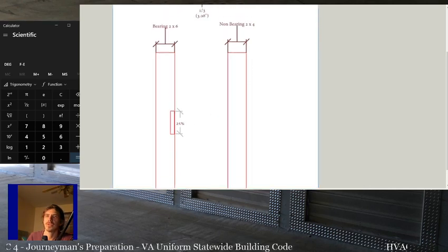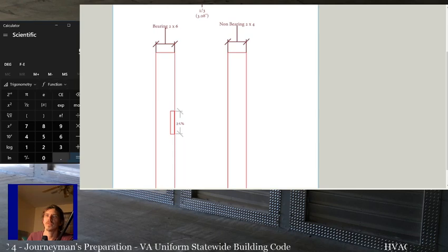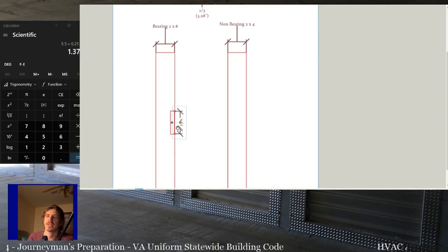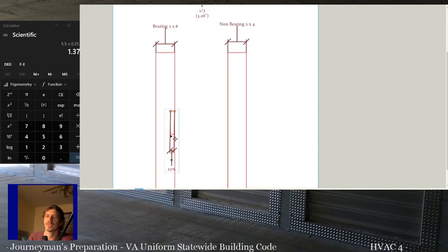So we need to do 5.5 inches times 0.25, and that will give us our notch. Oh, and I did it the wrong way again. The notch, it's how deep it is, right? I'm just kind of writing on the longest side. So this can't be more than 25%.